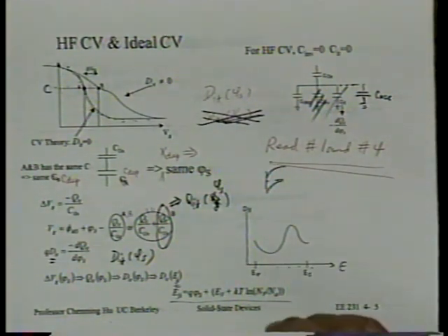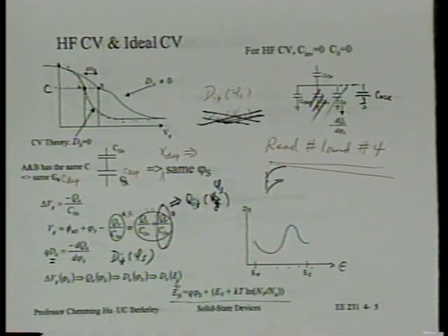Okay, that's number one. And number two, and I thought this is what you were going to ask, I'd like to make this point. Suppose we have an inversion layer present. Does that change what I earlier said about there being a finite time constant of the trap? When I said it's a finite time constant, is that because of an absence of electrons? I did not use those words. I used absence of electrons to explain why the inversion layer charge does not correspond to the high-frequency signal. I did say that, because of lack of electrons.